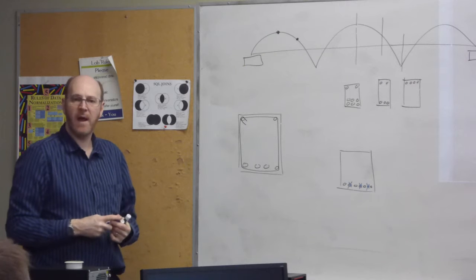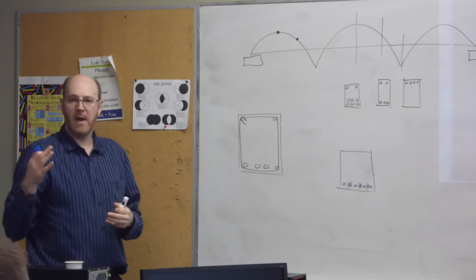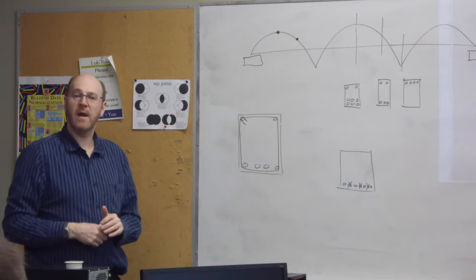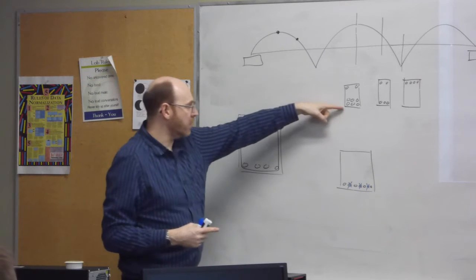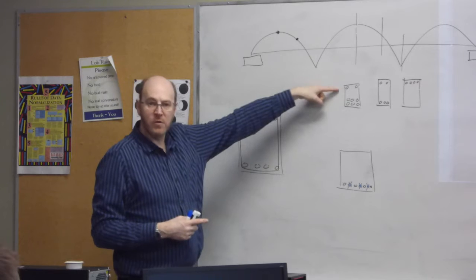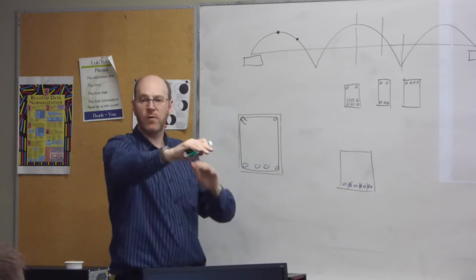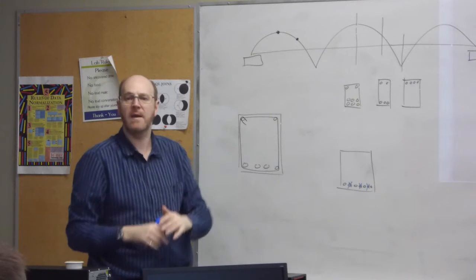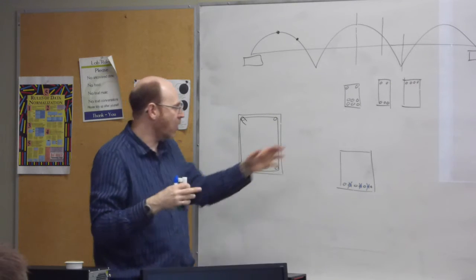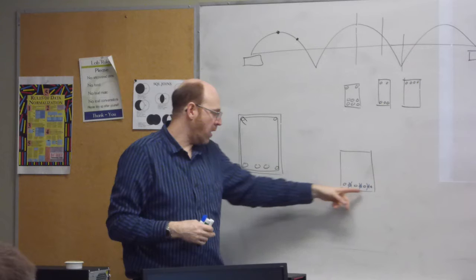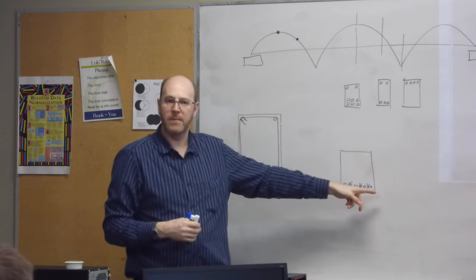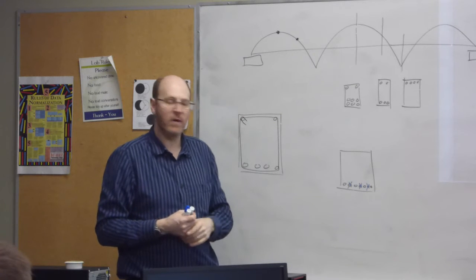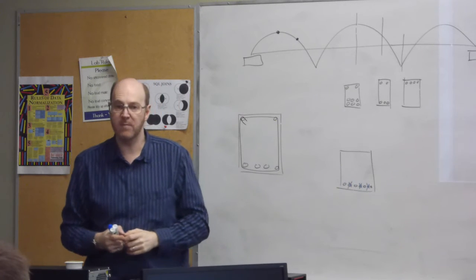So you can't have a pattern where I've got 4 bars going to 8 bars without adjusting the spacing, without getting kind of cramped, unless I go to a pattern where I've got 1 row of reinforcing, 2 rows of reinforcing. That second row of reinforcing is easy to add in there. So there I can have 4 on the bottom and then add 4 and get a total of 8. But if I've got it all on 1 row, it's an odd number and then an even number. So an odd number in the highest configuration and an even number in the lower configuration. And that kind of pattern works out reasonably well.